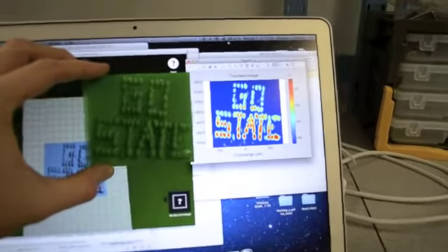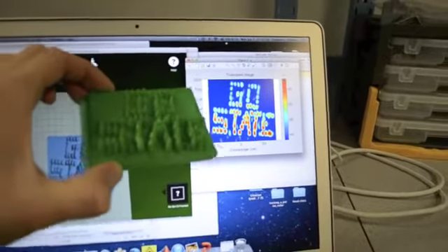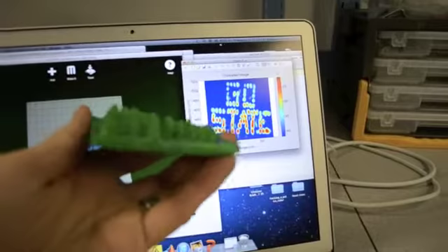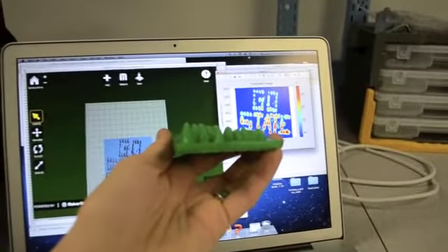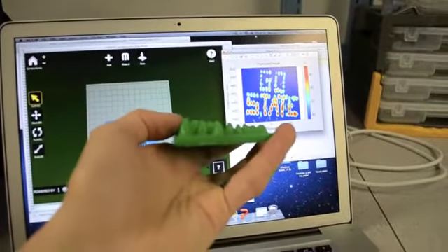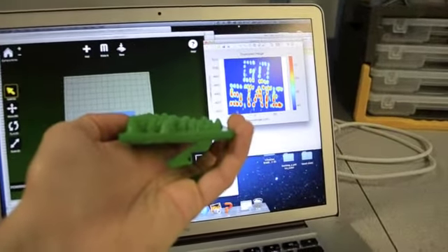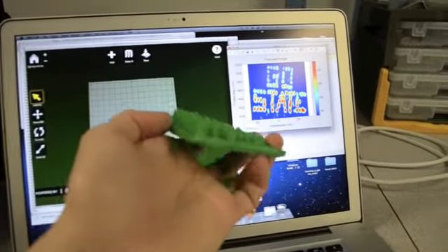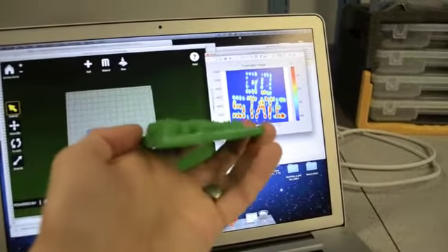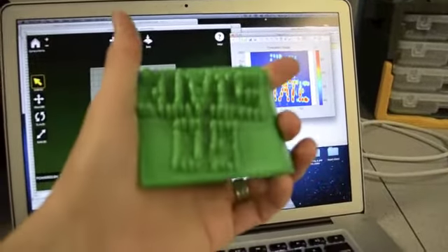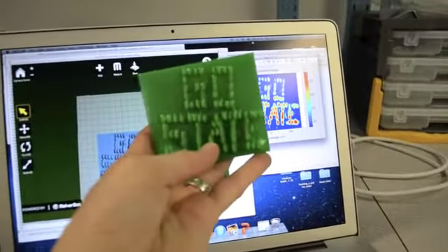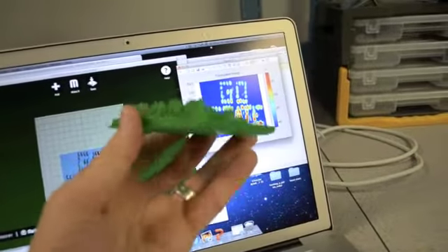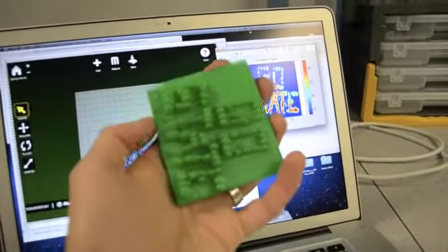It's a lot of fun when you take old radar data and actually plot it. Some interesting features are that you can see the height of the push pins. They're higher towards my thumb and shorter over here because the amplitude falls off with range. So you can see that. The other interesting thing is you can actually look at the sidelobe patterns. And with this, there's 20 dB of dynamic range plotted, or rather printed.